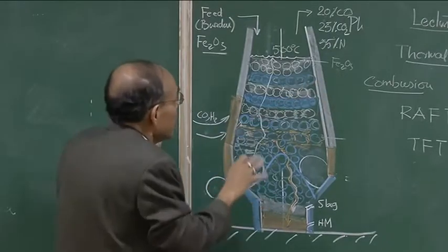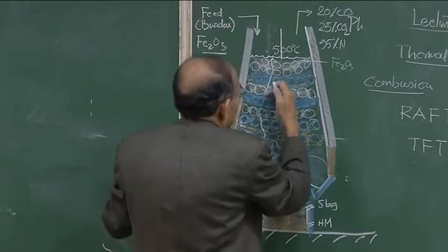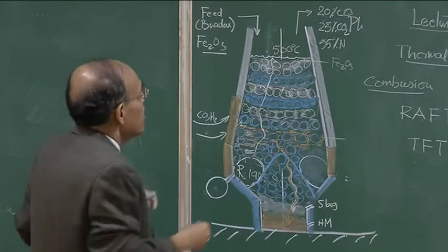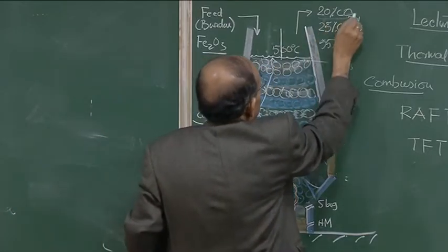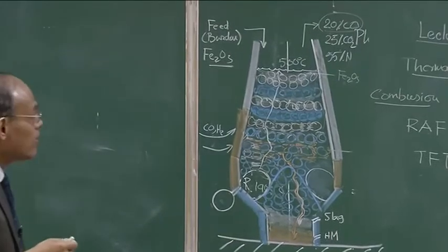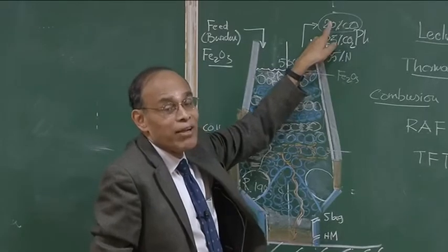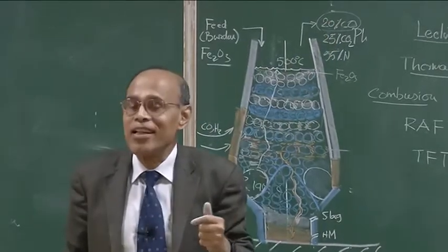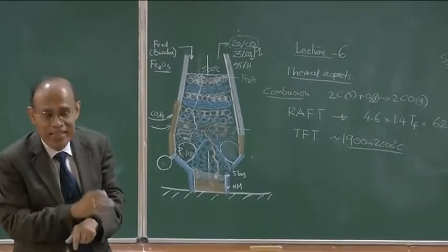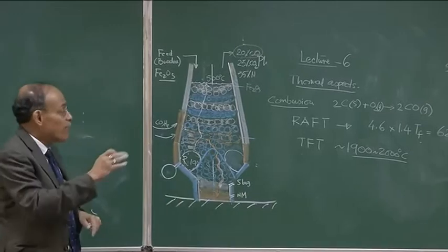So, virtually if the blast furnace is operated at equilibrium, with equilibrium stages established at various levels, then the final equilibrium will dictate that the carbon monoxide concentration is close to equilibrium. But that carbon monoxide concentration is not close to equilibrium, it is significantly higher. Essentially, it tells us that the potential of the gas has not been fully utilized, and the blast furnace is operated away from equilibrium.